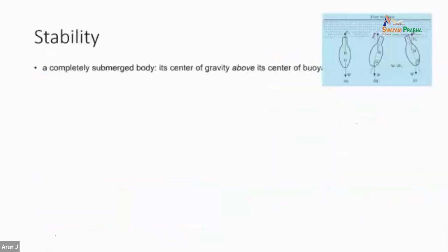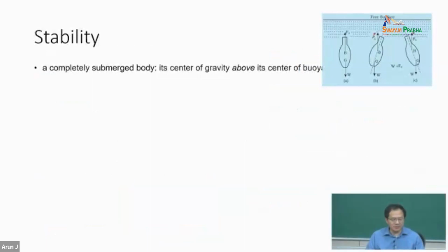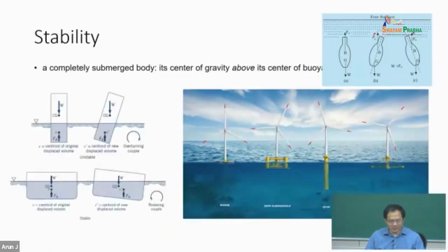Now, about stability. Stability is a very important concept in wave energy, and in any floating structure. Typically you think that if the buoyancy force center is higher than the gravity center, it is certainly stable. But it's not always the case.